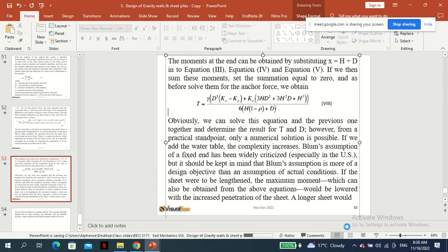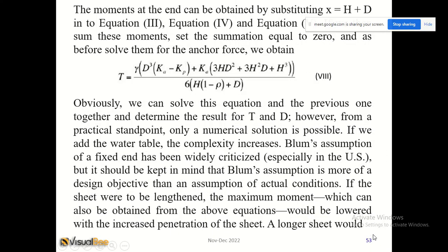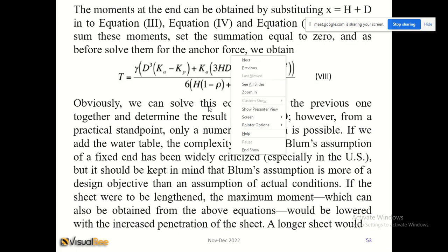Of course, we have to note the nature of the equations. I warned you yesterday that when calculating the penetration depth, even in the simplest form, we end up with a third-order cubic equation. Now when we add the tension, of course it's still third order, but you have to do some math. So this is better solved by a numerical method.